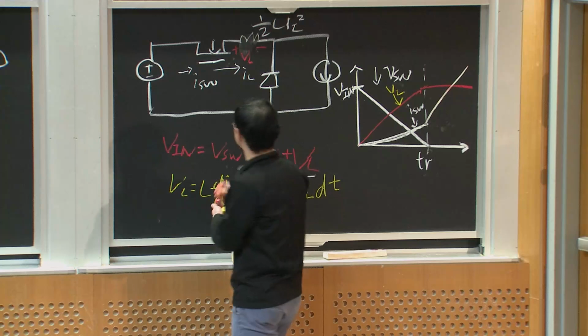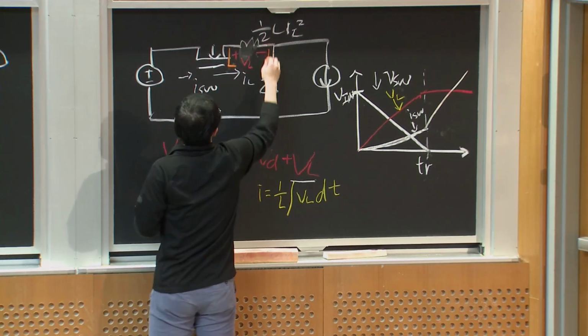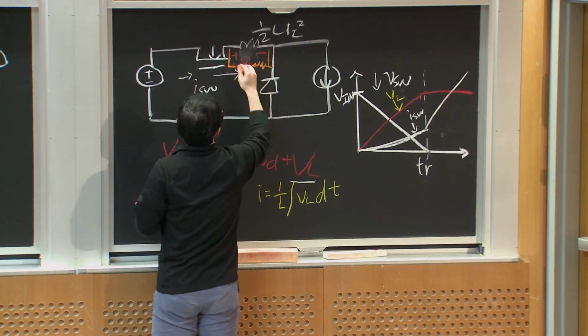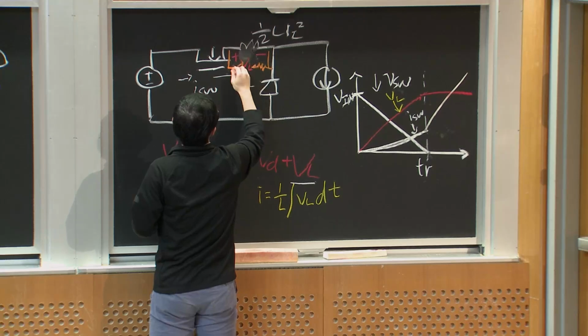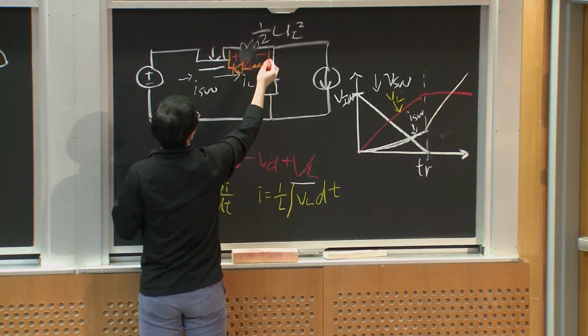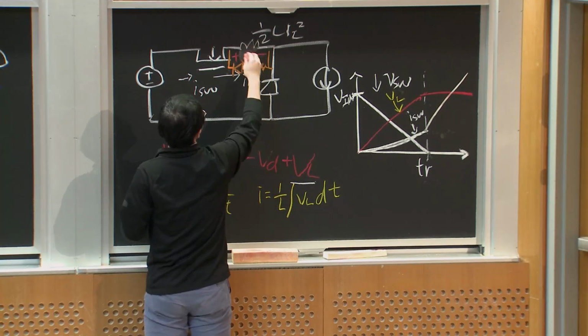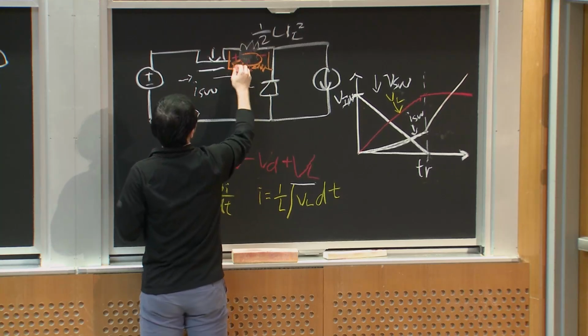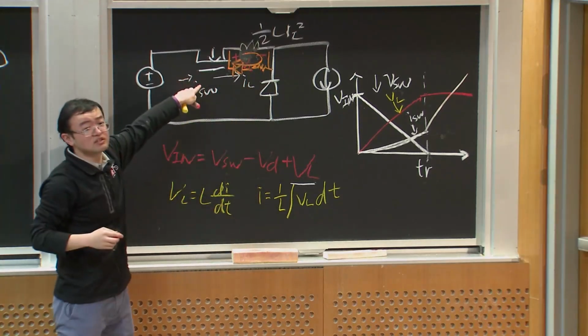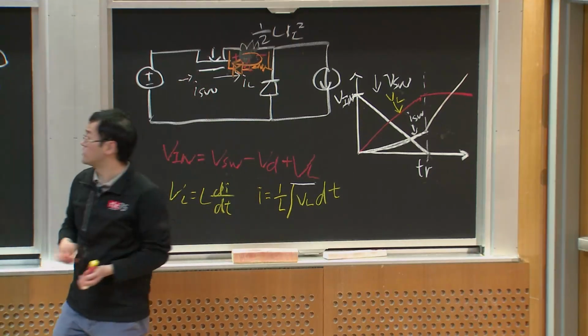And for practical use, we still have a resistor in series with a diode. And if we want to dissipate the energy of this inductor, we will have its current flow like this when the switch is turned off. So that's the beauty of the circuit.